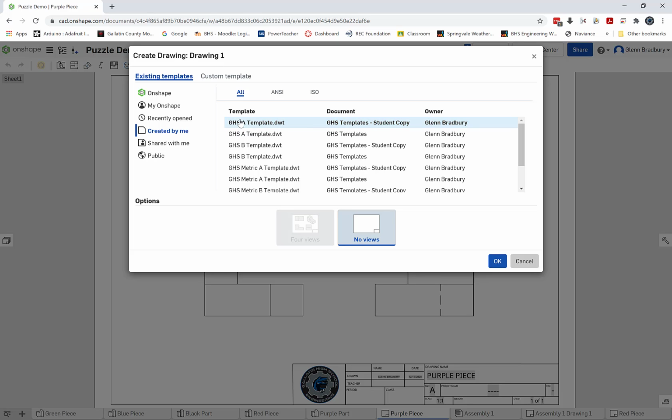In order for you to figure that out, what you might want to do is change the orientation. So to do that, it's pretty simple. You right click on the view and you say view orientation, and you just choose a different view. You choose one that you think might be better. So maybe using the top view as the front view might work out better. So you say top and then give it a second, and the program will reorient all 4 views for you.